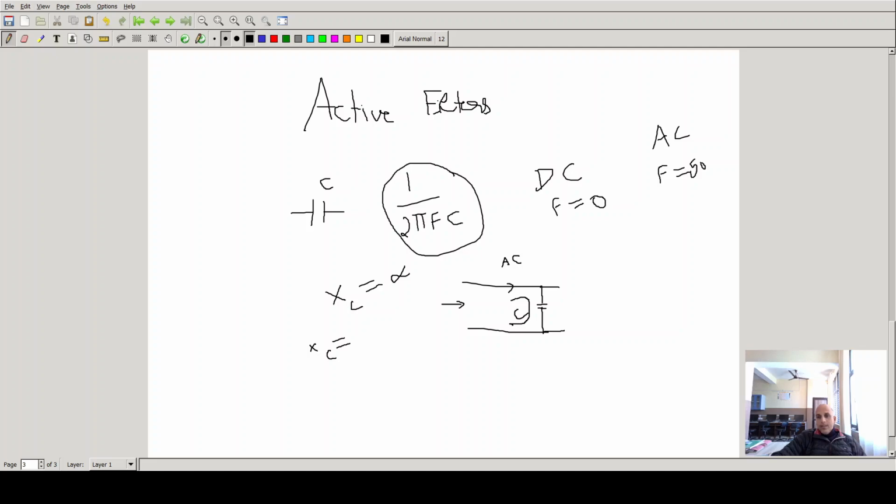So the alternating current can flow this way, because this electronic component is providing some opposition, or capacitive reactance, but it is not infinite, so current can flow. It is behaving like a closed switch.